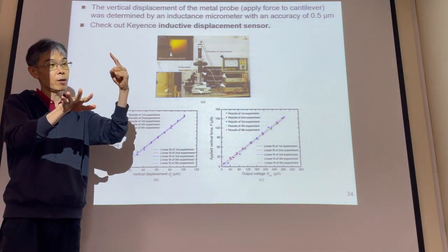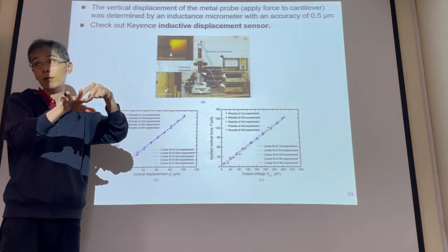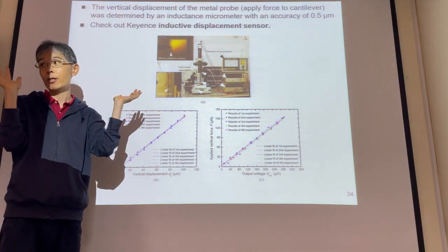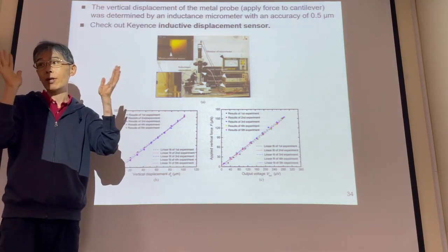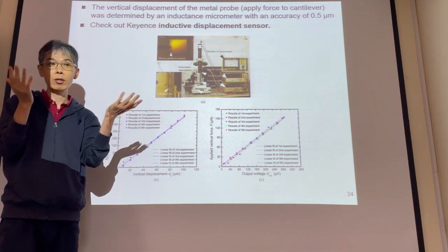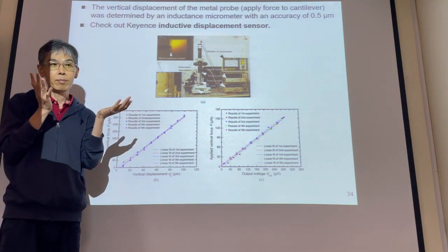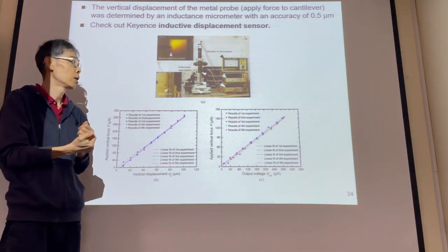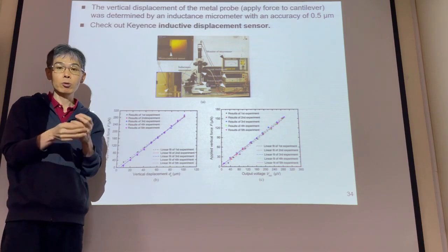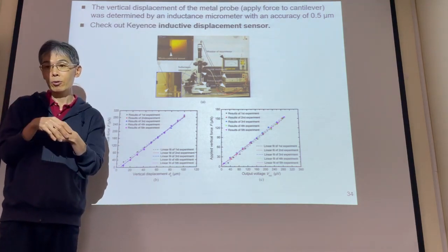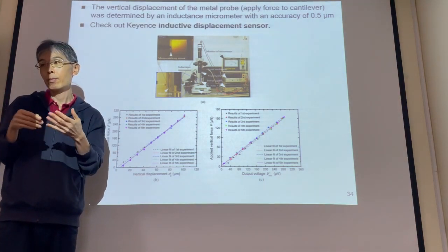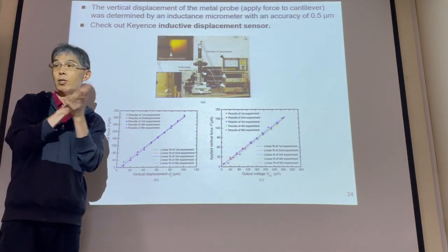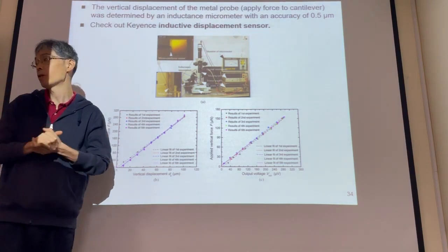Between the pad and the probe, we have contact resistance. The contact resistance might be very large, much larger than the resistance, so the result is useless. So we need to use a package, a good connector, to decrease the contact resistance or the wire resistance.